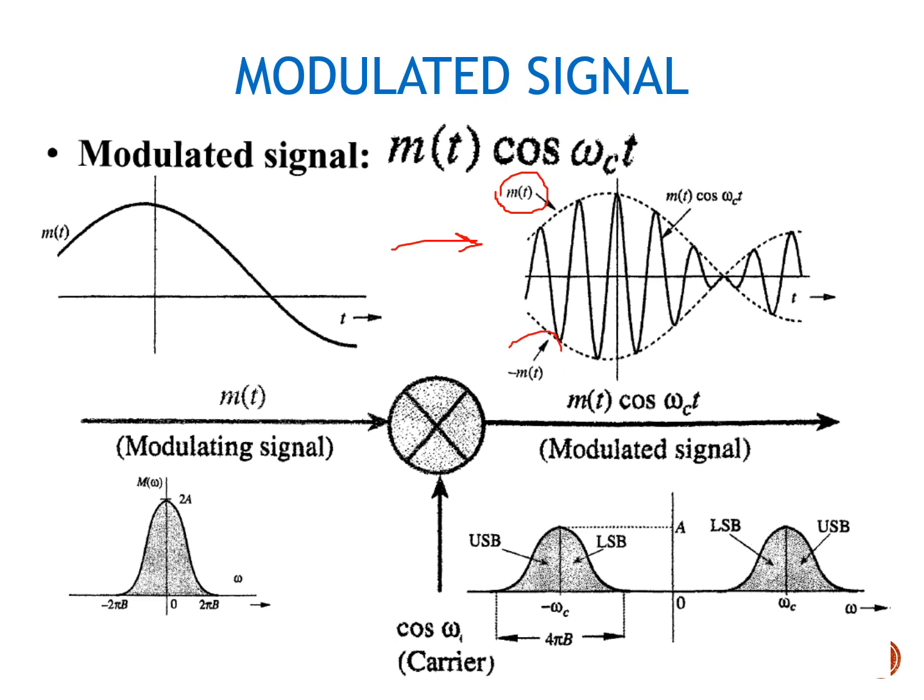Generally we forget to plot the negative side of the time domain plot. This comes from the multiplication of the negative values of the sinusoidal carrier. When we multiply it with this part of the signal, the overall result is negative, and so the time domain plot has excursions on both the positive and negative side.